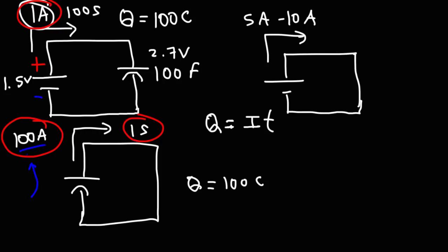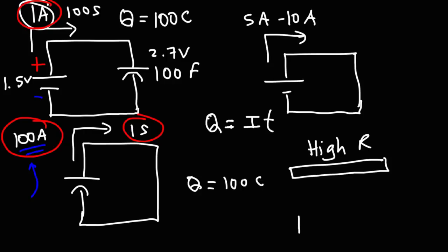Now, the amount of current that the capacitor can discharge over a short period of time depends on the conductance of the wire. A very thin wire has a large amount of resistance and a small amount of conductance. So if you were to use a thin wire, the current flowing through it will be less. If you were to use a thicker wire with a greater cross-sectional area, the resistance of such a wire is much lower, and so they can handle more current. So the bigger the wire in terms of its thickness, the greater the current that can flow from the capacitor.